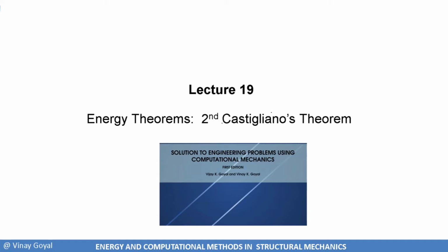And I demonstrated the Euler-Lagrange equations there happen to be the strain-displacement relationships, which is also insanely incredible because I didn't go through the kinematic derivations. I did it straight from the complementary principle of virtual work. Another exciting thing that we did there. And guess what? The boundary conditions that came out of the Euler-Lagrange equations were also telling us that the displacements need to be specified. So in other words, we've done some amazing things.